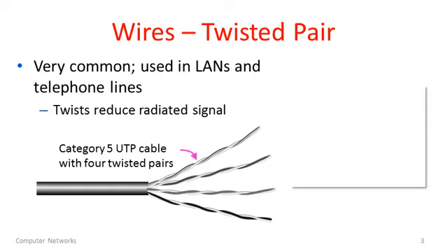This type of cable is used in structured cabling for computer networks such as Ethernet. The cable standard provides performance of up to 100 MHz and is suitable for 10BASE-T, 100BASE-TX (fast Ethernet), and gigabit Ethernet. Cat5 is also used for other signals such as telephone and video. This cable is commonly connected using punch-down blocks and modular connectors. Most Category 5 cables are unshielded, relying on the balanced line twisted pair design and differential signaling for noise rejection.